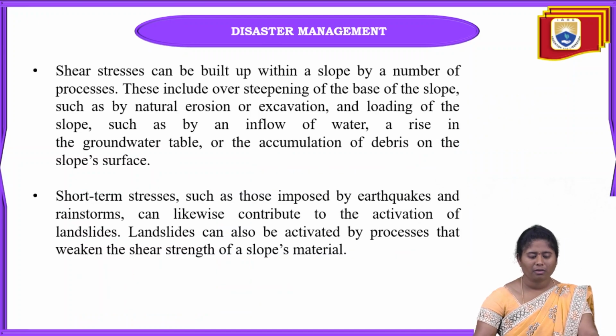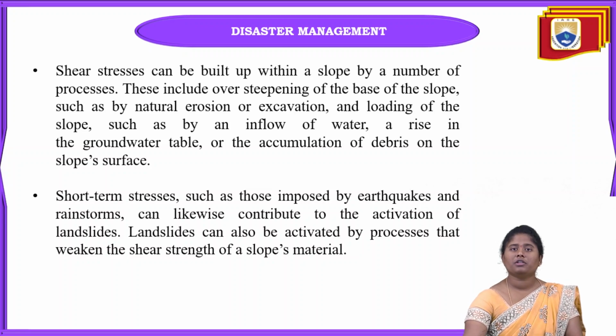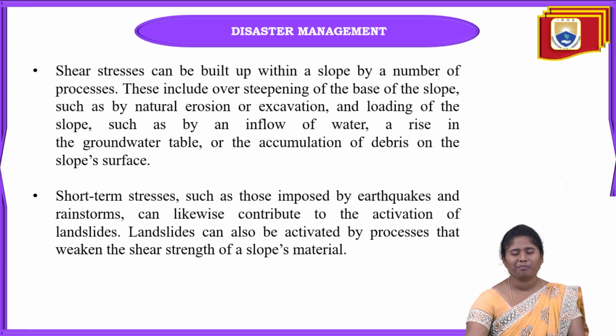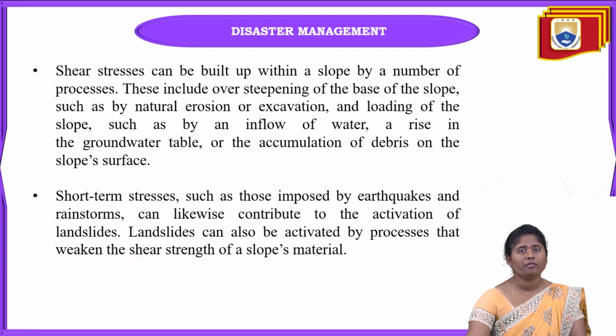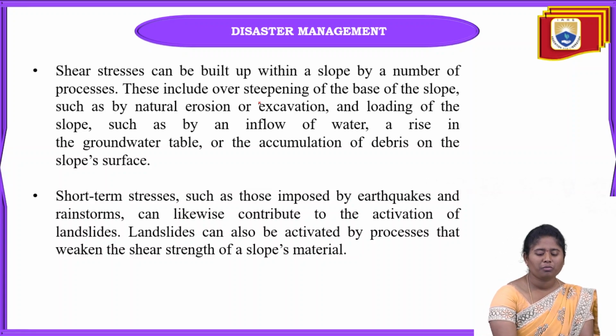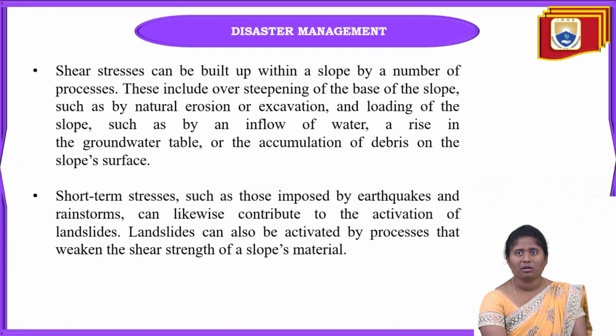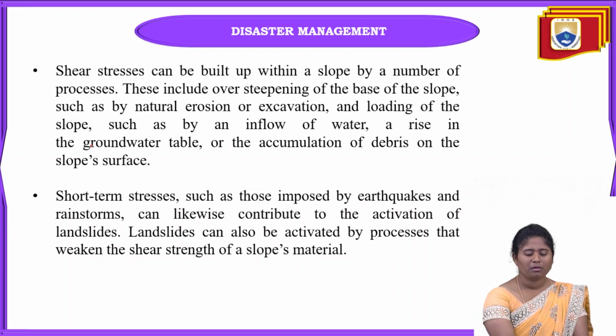Okay, shear stresses can be built up within a slope by a number of processes. Mainly this includes the steepening of the slope base, which occurs due to excavation and natural erosion, and there will be loading of the slope, meaning inflow of water and a rise of the groundwater table.